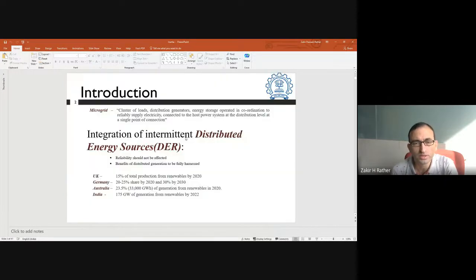I think this concept of microgrid you would have already covered through various lectures, so I'm not going into that. What I am trying to point out here is that even in a microgrid, one of the main focuses is that it is distributed generation based, meaning more renewable energy based, and therefore the number of synchronous generators or conventional or diesel generators in the microgrid is going to be relatively less. So it is going to be primarily dominated by what we call nowadays IBRs, inverter based resources, which can be wind generators, solar PV systems or battery energy storage systems, basically a source interfaced through an inverter.